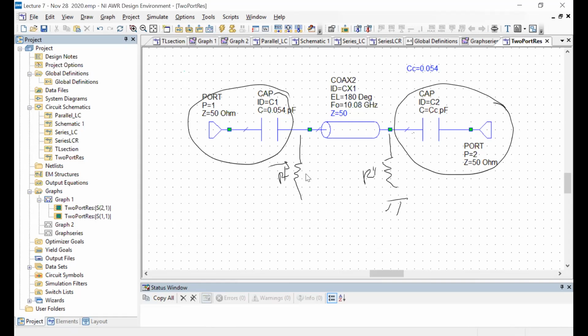And this middle section is not really doing an impedance transformation to connect those two, because too many things would be required. But at resonance, you still have a resonance, because there is still a special frequency where the energy buildup is maximum. But now you don't have perfect transmission at resonance. So quantitatively, this second argument looks somewhat nicer.